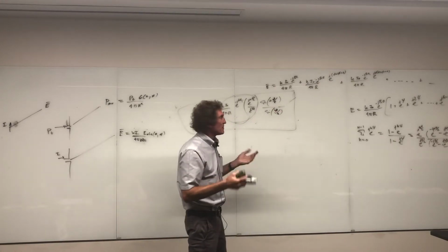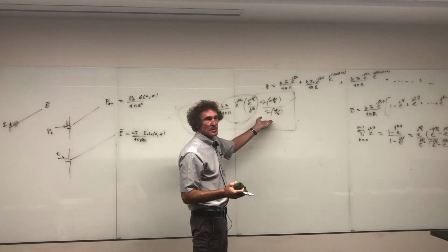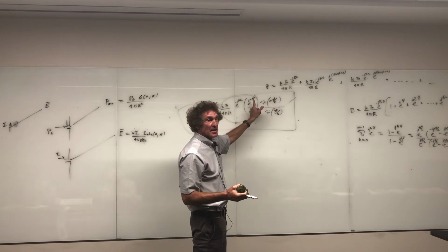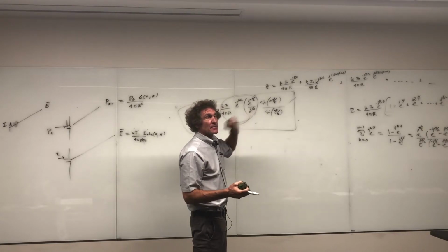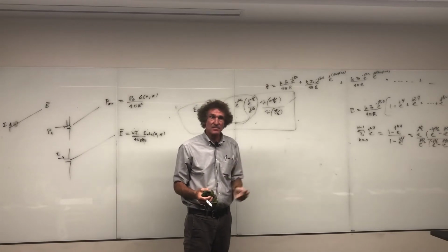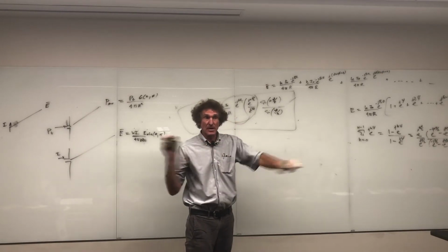If psi is 0, isn't this indeterminate? Well, then you take the derivative top and bottom, and you're going to get an n over 2 and a 1 over 2, or 1/2 n. The effect of the array is that the electric field is magnified at its maximum value by a factor of n, the number of elements.